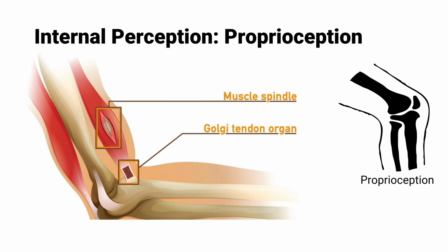And to answer the question I asked you before, how do you know you're standing upright, right? This helped you understand how we are touching our nose. But to stand upright, we have an internal measurement in our ear canal, which lets us know the direction of gravitational force that lets us stand upright. Okay, so again, these all come into proprioception, and the equivalent of our ear canal stuff in robots is called an inertial measurement unit, and the equivalent of the muscle spindle stuff is called a motor encoder, which lets the motor know how much it's turning.